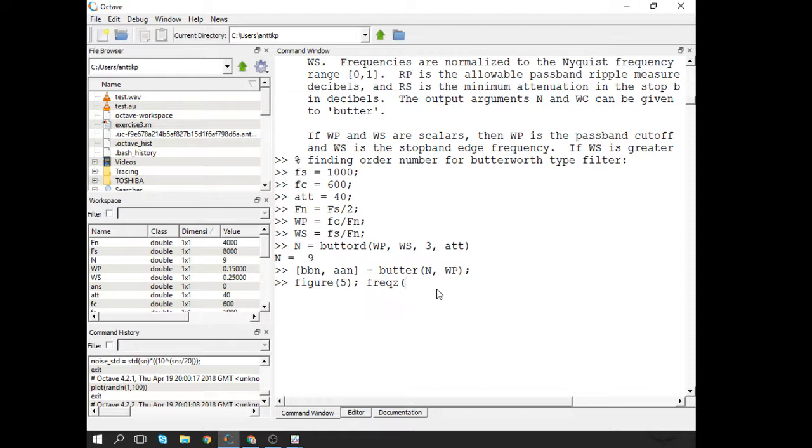That's the BUT-ORD is just making the estimate, and this is actually because of the bilinear transformation, you need to tweak the cutoff frequency a little bit. I think it gives the tweaked cutoff frequency, but yeah, better use that one. Maybe. Try it, see the difference. Well, this is not science, this is engineering.